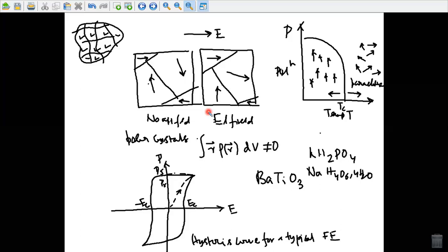Ferroelectric crystals with hydrogen bonds, that is KDP, KH2PO4, which was the second ferroelectric crystal discovered, undergo an appreciable change in transition temperature when the crystal is deuterated. BaTiO3, shortly named as BT, was the first mechanically hard ferroelectric crystal that was discovered. Ferroelectric crystals are often classified as displacive, involving lattice distortion, that is barium titanate BaTiO3, or order-disorder transition.